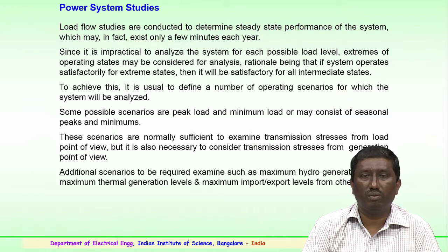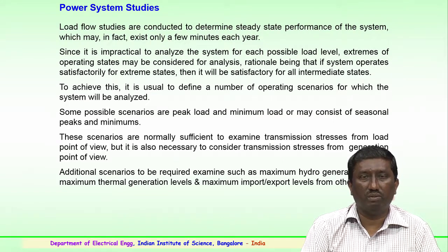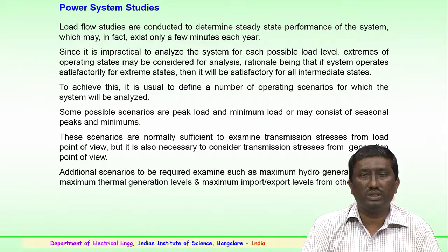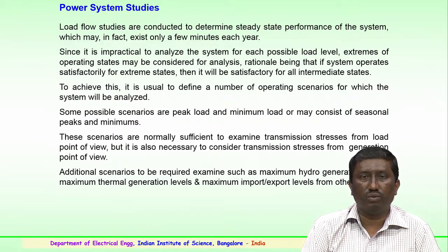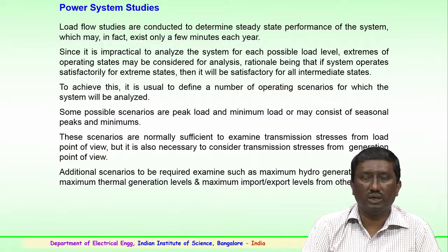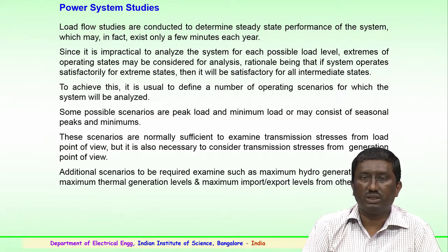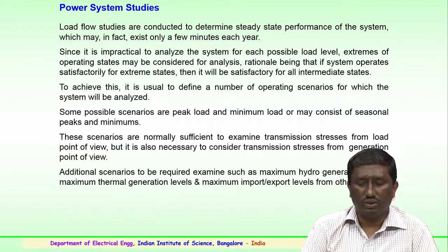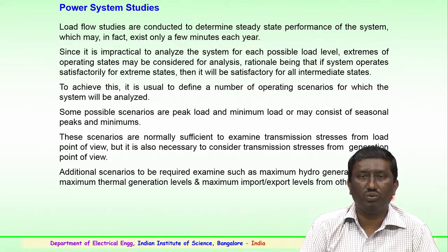This peak load, minimum load of that substation, depending upon the seasons, the data has to be available. The scenarios are normally sufficient to examine transmission stresses from the load point of view, but it is also necessary to consider the transmission stresses from the generation point of view also. So, all the stresses pertaining to the transmission from the load and from the generating stations point of view are also to be considered during the power system studies.